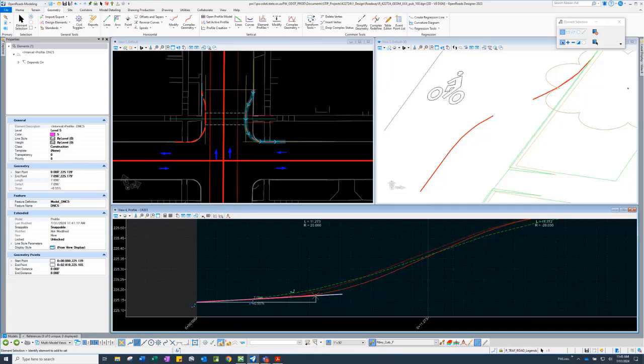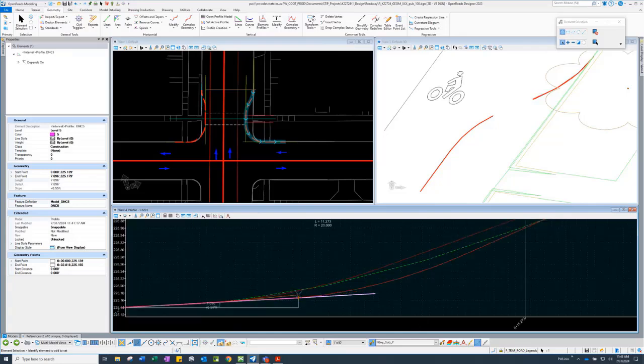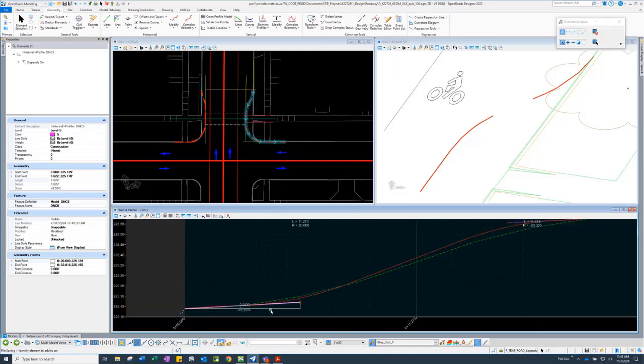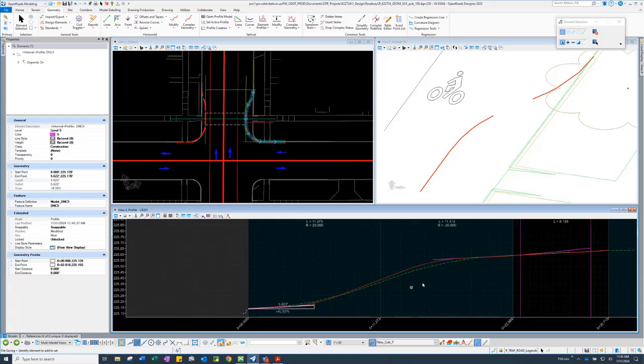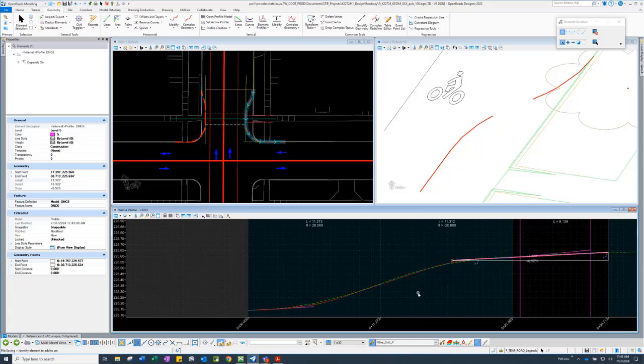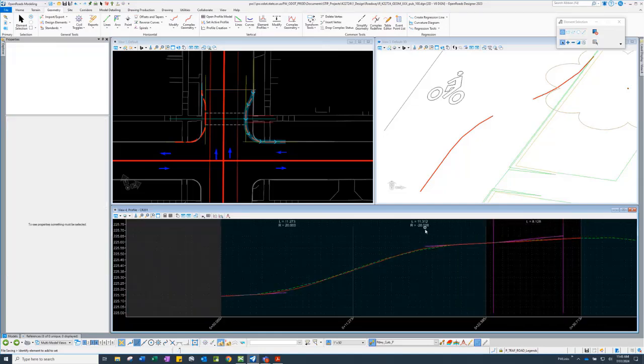So as you see here, I can move it over and it moves that line. I can, without having to touch the profile itself, hold that tangent line, the slope of that tangent line. Right. Super helpful. So you've got two constraints. One is slope, the other is length, and you are adjusting the length and maintaining the slope. Same with this side. So I can move it over to fit it in much better. As you like to say, gooder. Yeah. So now I have a ramp curb line.